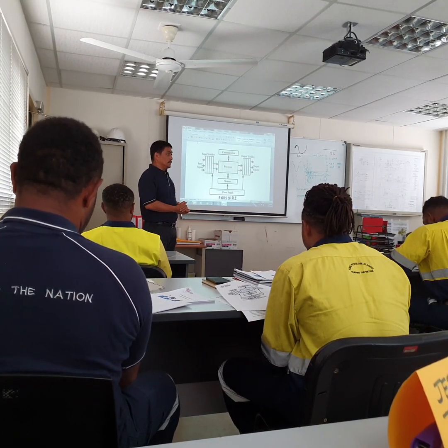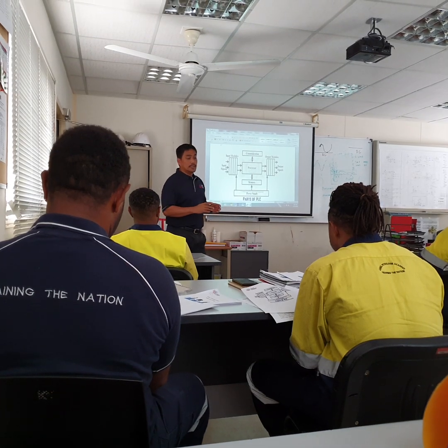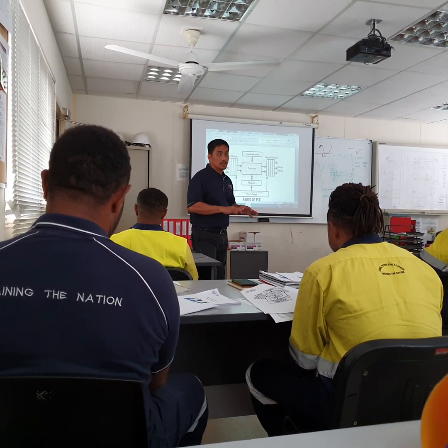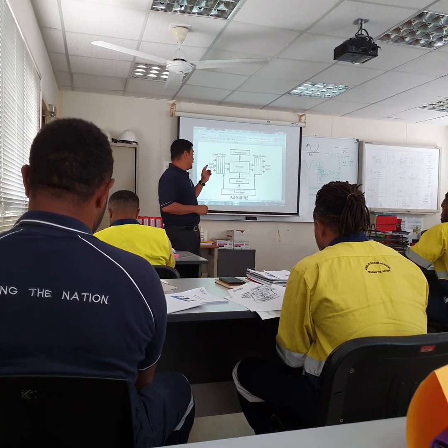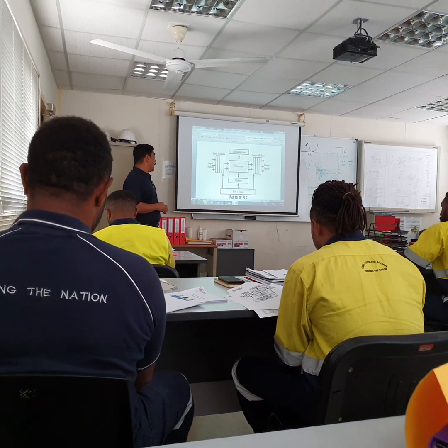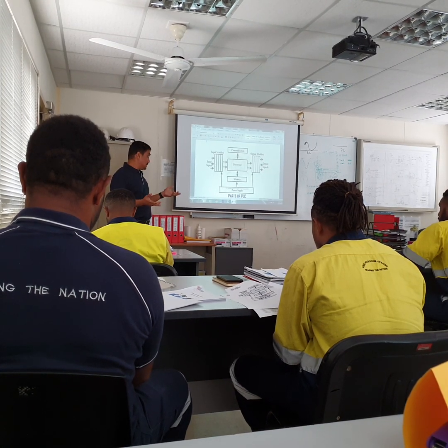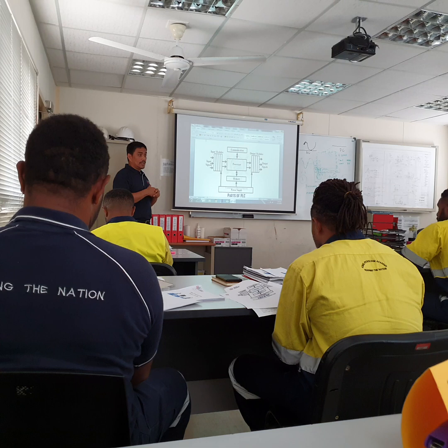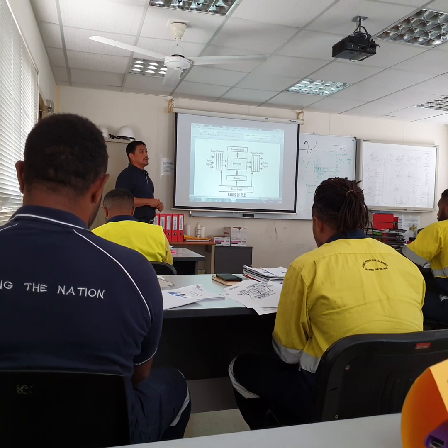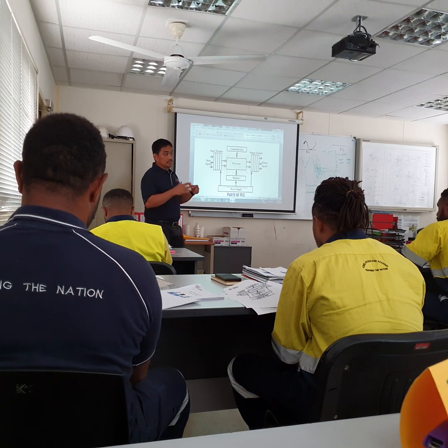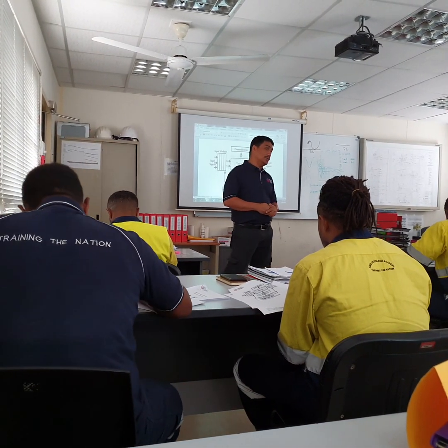Digital output means it's like a switch on, off, like a bit 0, 1, 0, 1. But if it is an analog output module, it will give some voltage, resistance value, or even certain current value.